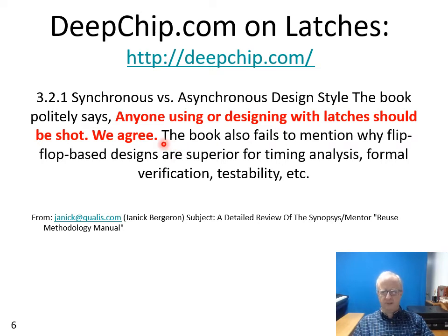And I should be careful to say, when we say latches here, we're talking about level sensitive latches as opposed to edge triggered flip-flops. You'll find in literature, in industry articles, in textbooks, like when you take 437, they will use the word latch in a more generic sense. But in 337, we specifically mean level sensitive devices.